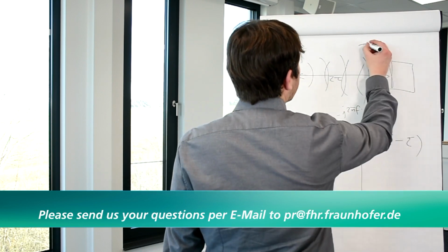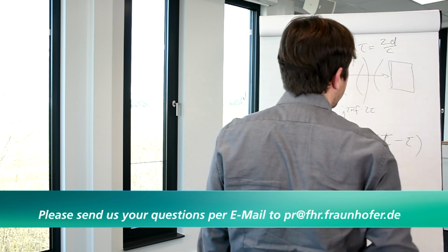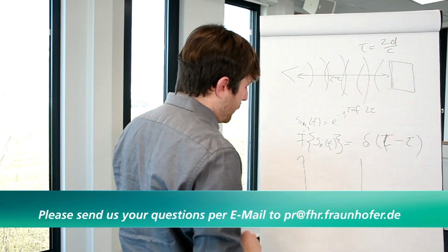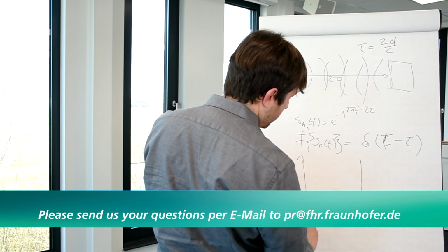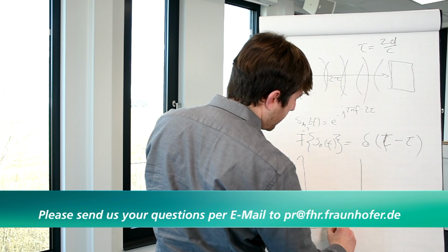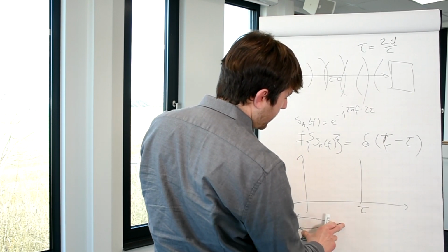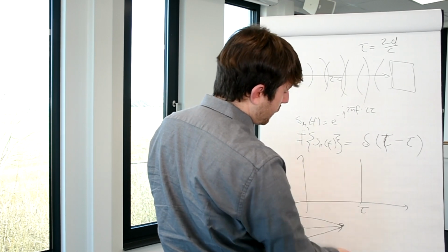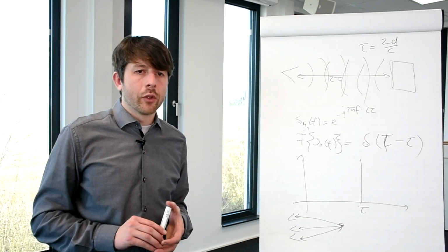What is the delay? The delay is just 2 times the distance divided by the velocity, and that's why you get the distance. If you now take lots of antennas, you get many distances. We compensate the phase for the direction, and so you have your distance information as well as your angular information. That's the fundamental concept of that.